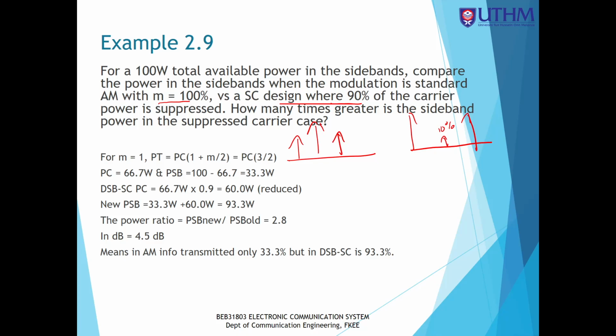Remember previously, when we suppress the carrier, theoretically we increase the sideband amplitude. Theoretically, when we suppress the carrier, it looks as if some portion of the carrier goes to the sidebands. Seolah-olah portion suppress itu pergi kepada sideband. Okay, ini secara theoretical. Macam kita lihat tadi, amplitude becomes VmVc over 2 when we suppress completely.